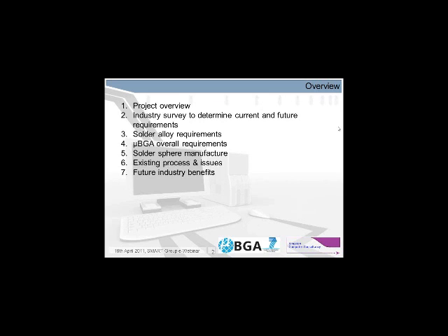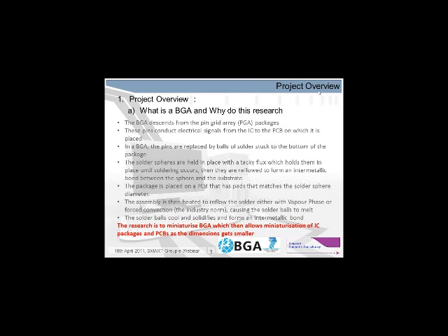A quick overview. I think a lot of you will probably know what a BGA is, but just to make sure we're all roughly on the same page, and why we're doing this research. The BGA descended from the pin grid array. The pins in the pin grid array, the PGA packages, conducted electrical signals from an IC, an integrated circuit, to a PC board, the PC board on which it was placed.